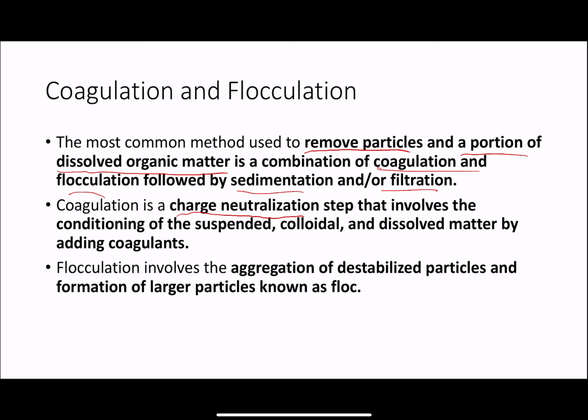Because we are doing charge neutralization, we are also conditioning the suspended, colloidal and dissolved matter. We are preparing these solids for something else later on, which is flocculation. So coagulation is a charge neutralization step.